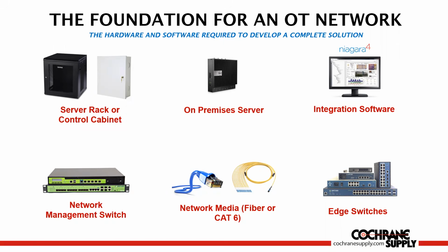Now, like I said, our industry is moving to IP devices, which requires Cat6 cabling, right? These controllers are networked together with Cat6, as opposed to BACnet MSTP devices, which are being slowly but surely phased out and use RS-485 cabling.